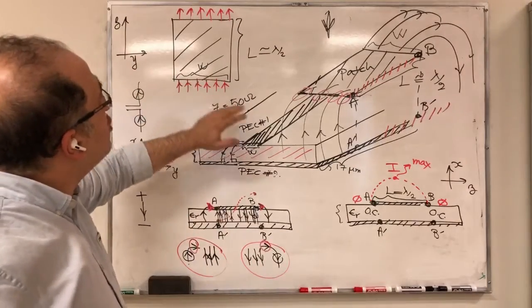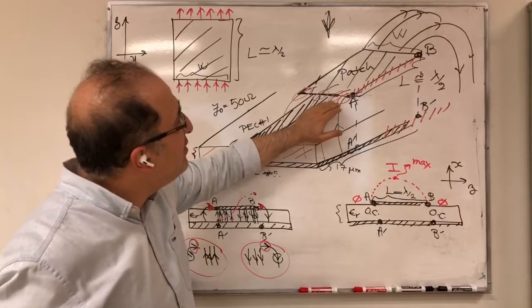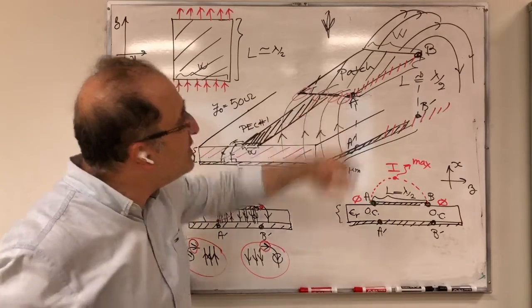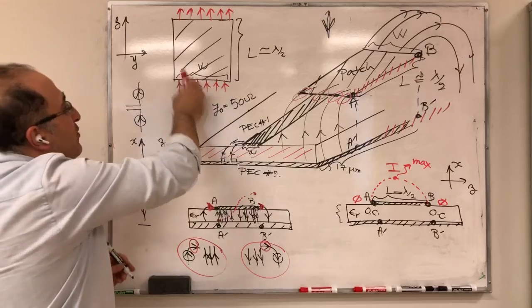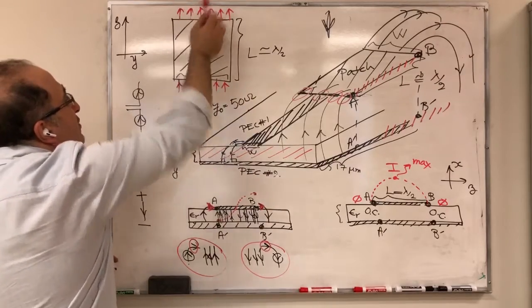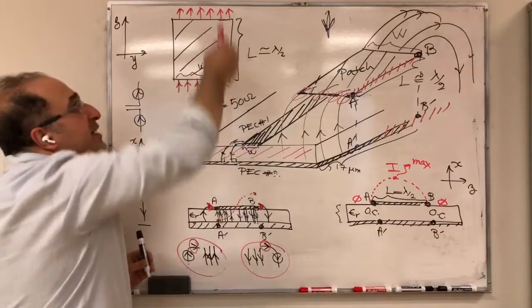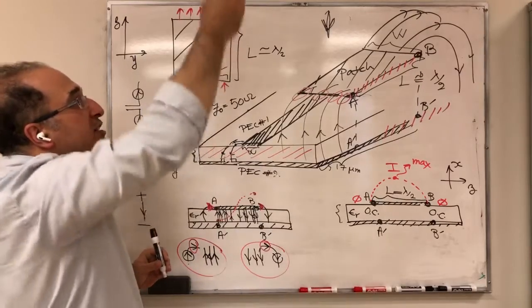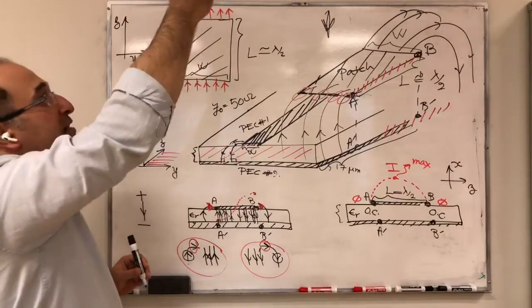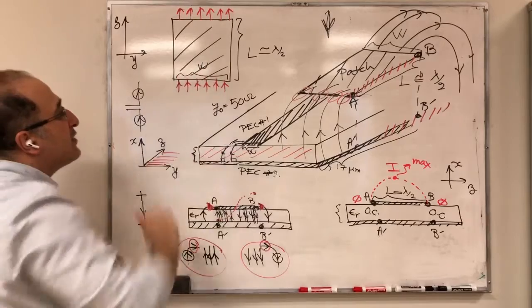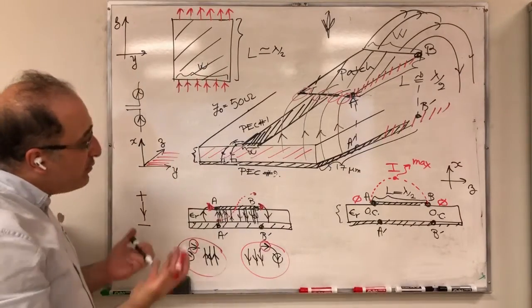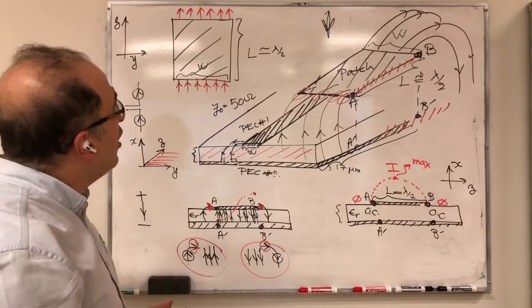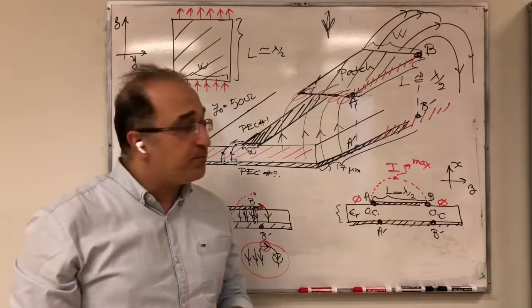Based on that, you can even understand the polarization coming from this patch antenna: because you have these electric fields in phase here and here, it is linearly polarized, in the direction of these electric fields. So that's one way of looking at our patch antenna.